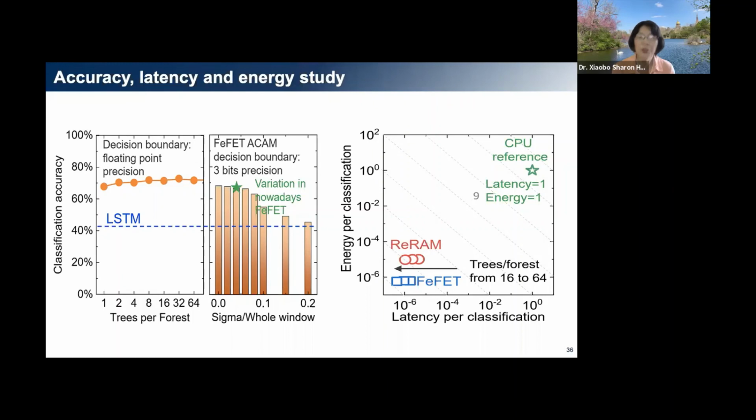Yes, we could use them for intermittent computing, but currently most of the non-volatile memory has one drawback, and that is they are expensive to write, right? Even without verify, they tend to use higher voltage, and they also tend to have longer write time. That's one place they cannot beat CMOS yet. RRAMs, FeFETs, they all have this problem. So unless your intermittent time is really long, if you have to keep writing them, then that's not worth it.